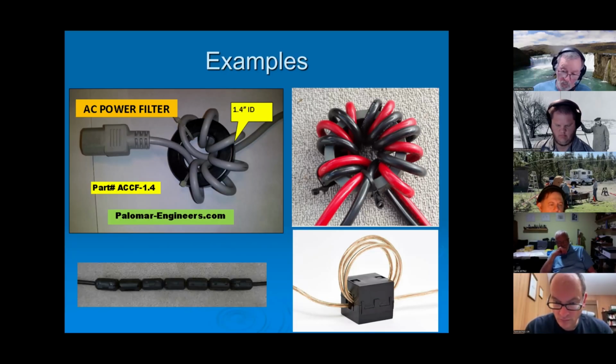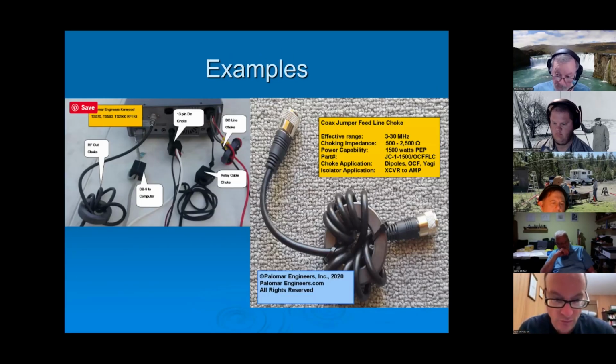Now, one thing I'll mention here is that ferrites don't stop the RF, they attenuate it. So all the stuff that I showed you, those are what happens when it attenuates that signal. So you still have RF energy getting through. The question is, can you get that RF energy as low as possible so it's not interfering with things?